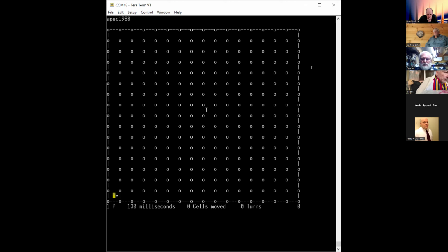So if I just show, with a bit of luck, if this all works, what happens when I take the first cell out of the queue, you can see I've marked, yep, it has worked. I've marked the 4 cells next to the T with an S, which means they're solved. The mouse doesn't know about any walls in this area at the moment, so that's what it does. And I can keep going there. You can see I've done it again. So I've taken the cell north of the T, which was the first one in the queue, taken that out of the queue and put 3 new cells in the queue adjacent to that. Okay, and I can keep doing this.